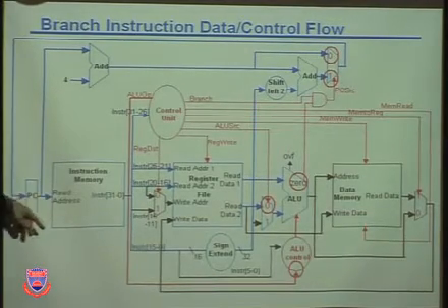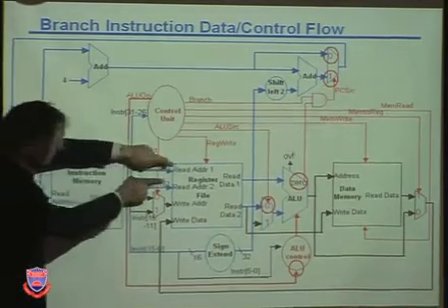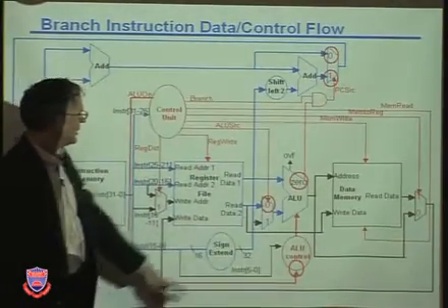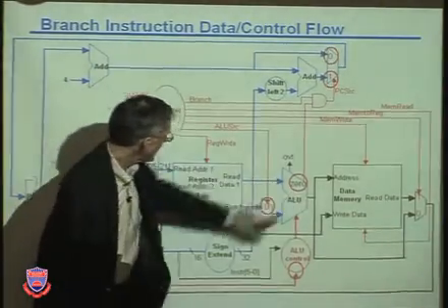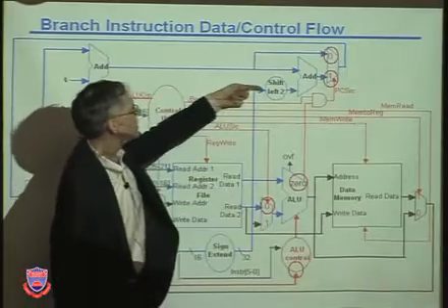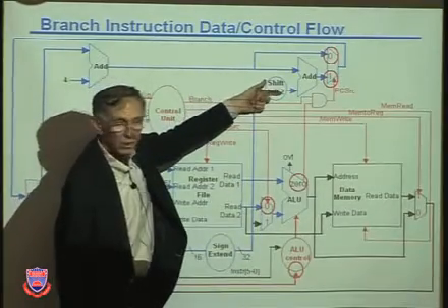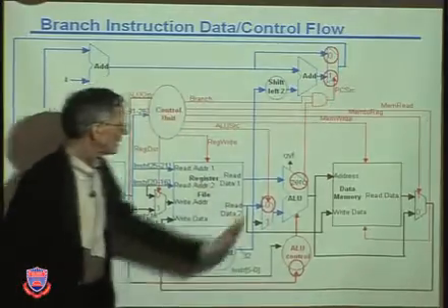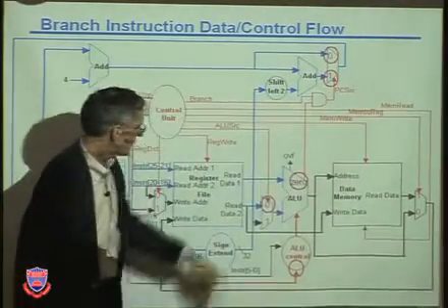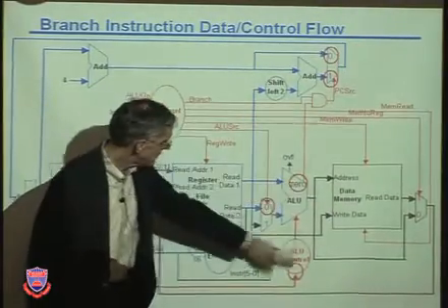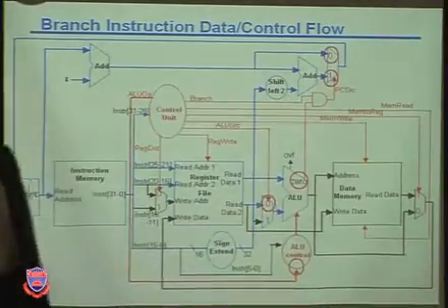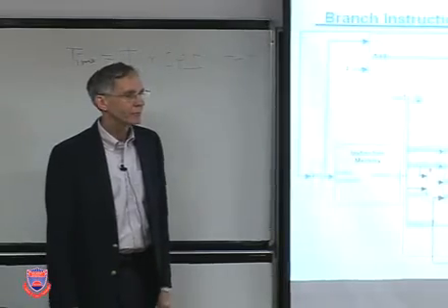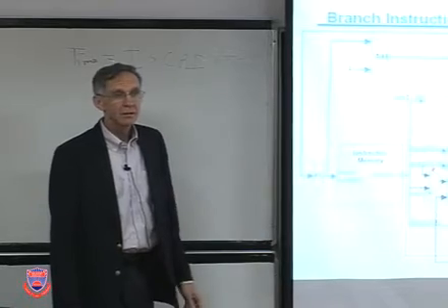Okay, and what else was blue here? Well, obviously, these two guys are blue, and the sign extended immediate. The sign extended immediate isn't for here, but notice where else it goes. The sign extended immediate goes up here to be multiplied by 4, to be added to PC plus 4 to create the branch address. None of this matters. You don't see any circles over there, but we do need to, that matters, and that matters, and that matters. So we see how to control and execute a BEQ instruction. Any questions about this? Okay.